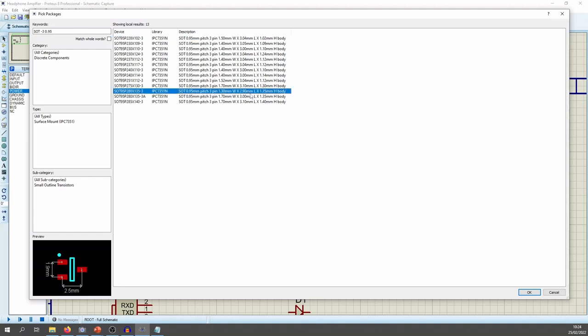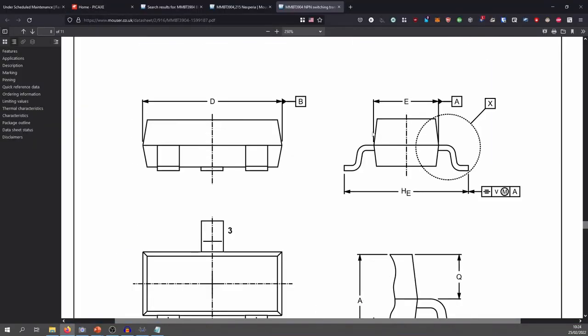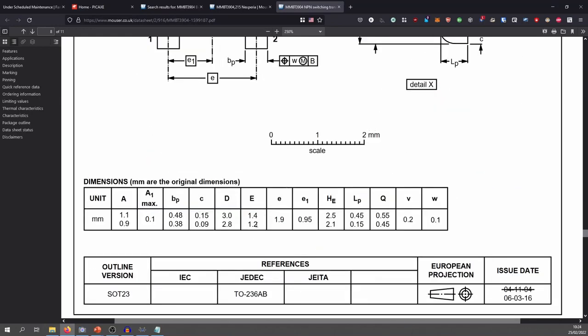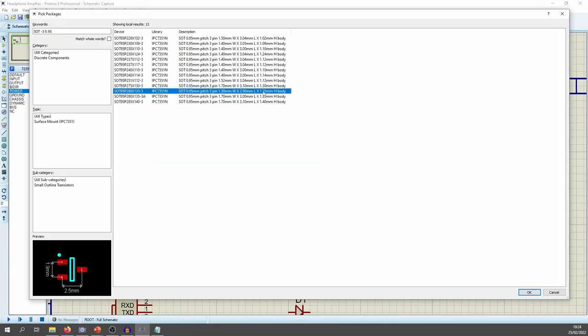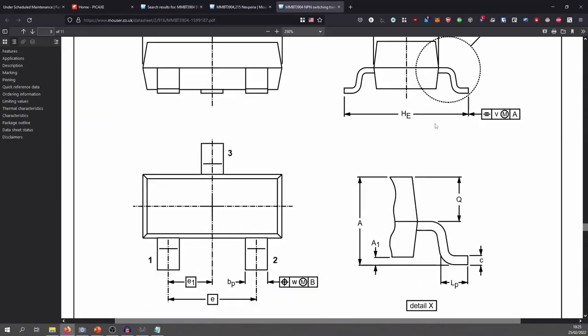So we've got a 2.9 there, so we can check whether, can you see that? 2.9 width. Let's look at the other dimension, E, is between 0.12 and 0.14. That's pretty much, we're good there. And the height, you might not necessarily match identically, because some heights are slightly different.